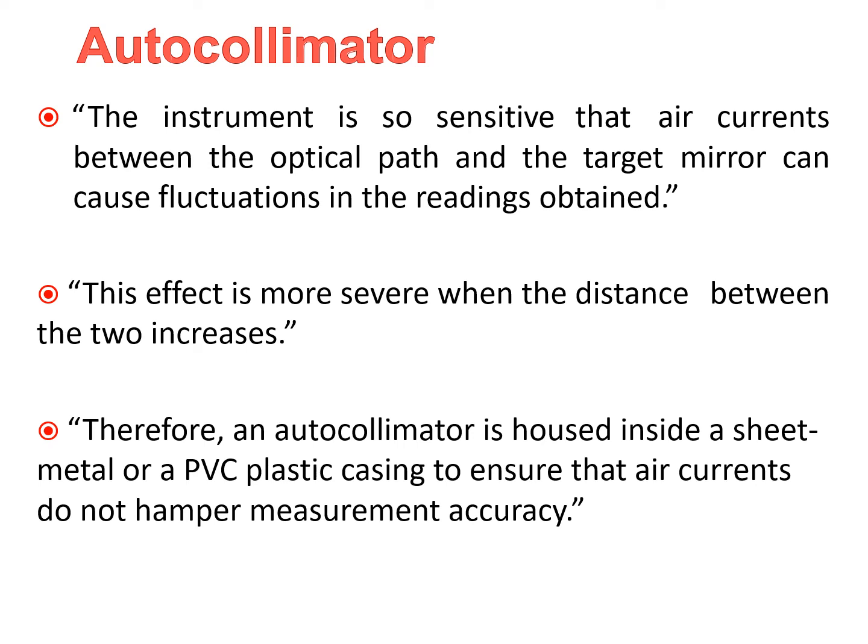The major points we have to observe are the focal length, which determines the sensitivity and the angular measuring range of the instrument. The longer the focal length, the greater the measuring sensitivity and accuracy. Objective size, that is the lens size: when a large objective is used, light conditions are more favorable and the evaluation of results is easier and more accurate. The beam splitter we are using gives the corner cubes. A physical beam splitter is recommended in most cases due to the larger measuring range.